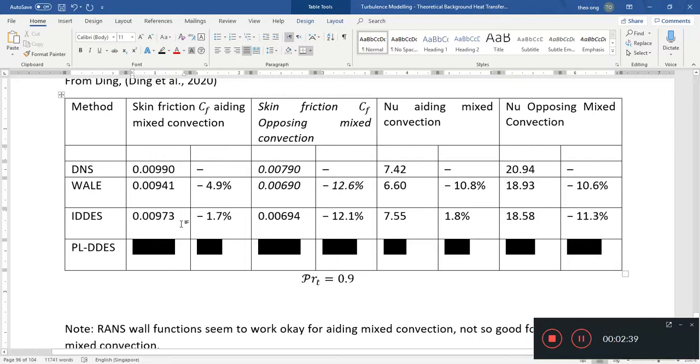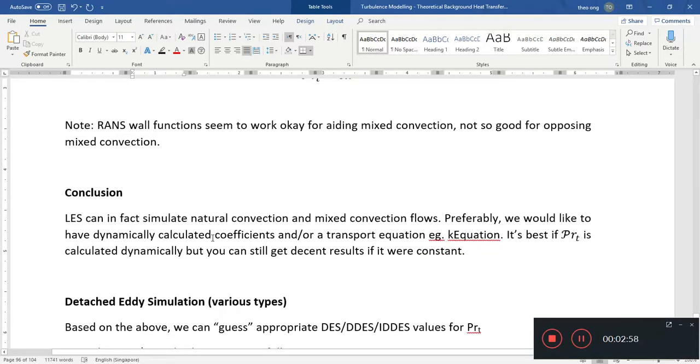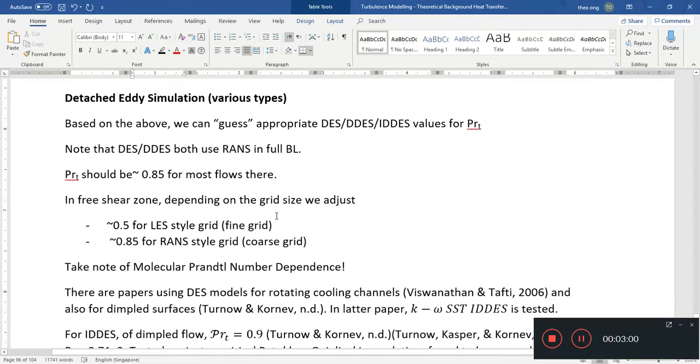Of course, if your fluid is generating heat, for example in the fire case, then you may want to take note of these dynamic Prandtl number models as well. But that's for the special case of fire or reacting flows, where some kind of reaction is producing heat. So that becomes more important in the bulk flow if your flow itself is producing heat.